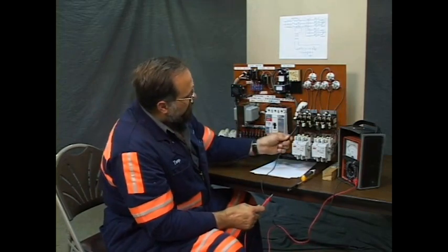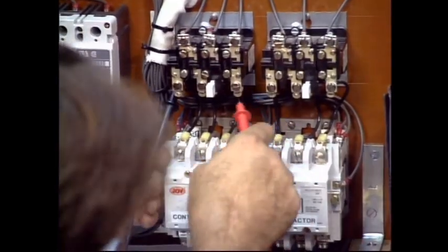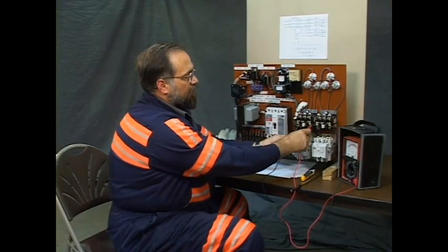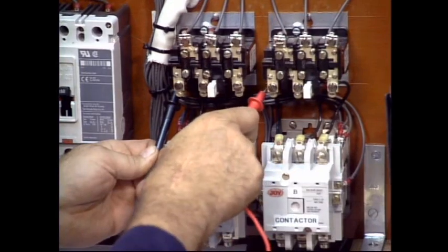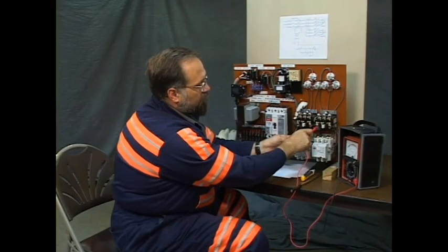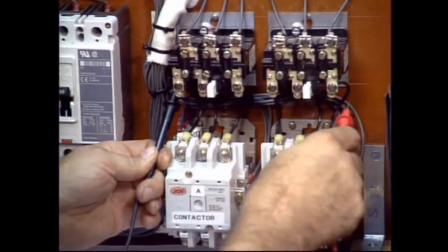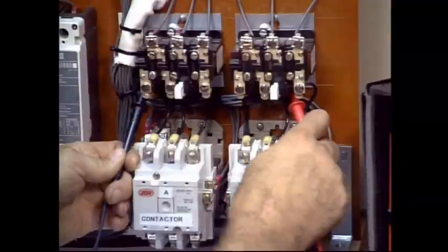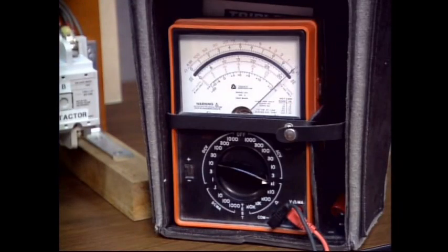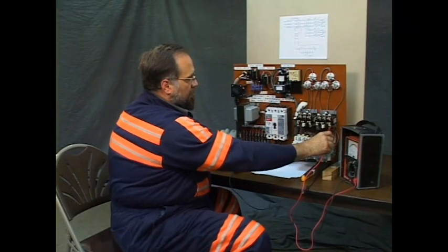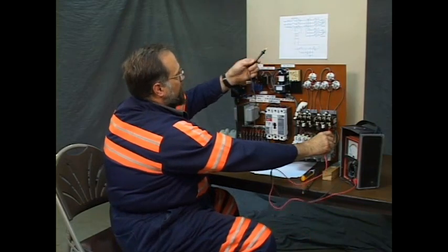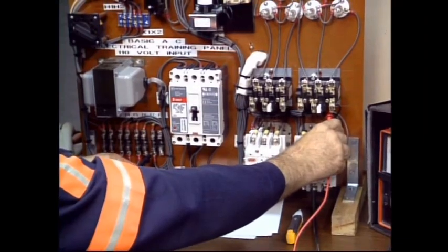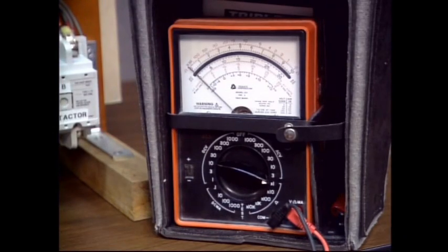We need to find this one quick. We're running out of parts to check, aren't we? Looky here. I'm going to read through the overload relay. It reads good. No problem there. I'm going to go to B overload, and that's still good. Finally to the other side of B overload. Again, look at that meter. There's no resistance. Well, from B overload, the next point on the print, BOL goes to the load side of an F7 fuse. Uh-oh. Now that's no good.